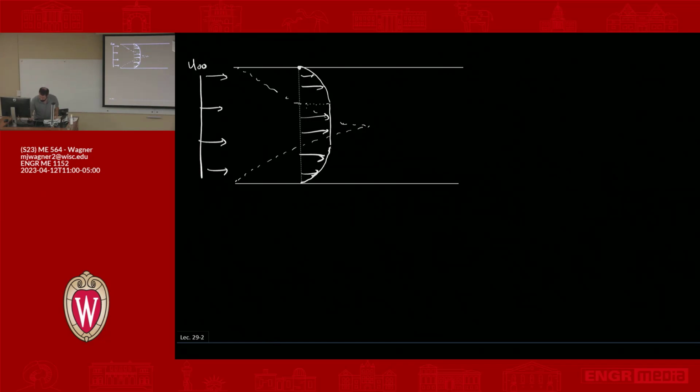So okay, that's that position. Let's look right at the position here where the boundary layers merge. So what does the velocity profile look like there? Well, it would look kind of like this, and then the same thing on the other end. So again, you have the no slip condition. But right at the middle where they meet, you have the same velocity slope. So it's this kind of parabolic shape that's perfectly symmetric.